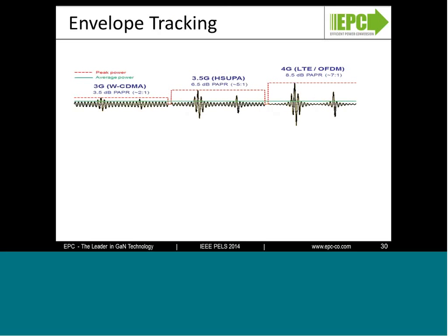inside the signal. So when you look at going from, on the left, a 3G wireless signal, all the way on the right, we have the new 4G LTE signal. You can see that the way they're packing more information in is they're essentially using different techniques. And what that will induce is a higher peak to average power ratio, or PAPR.